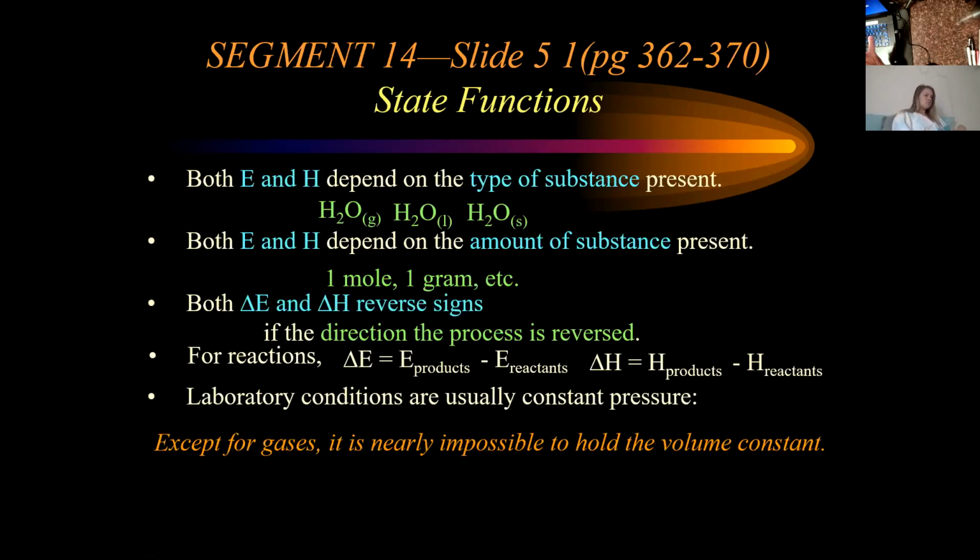And it depends on the fact that when you push on a liquid, you can't compress it. If you could compress the liquid, for example if you get air in your gas line, in your brake lines, you push on the brakes and you don't stop so good. And in the old days, when it wasn't all electronic, you could actually feel it spongy when you put your foot on the brake. The brake pedal would feel spongy.